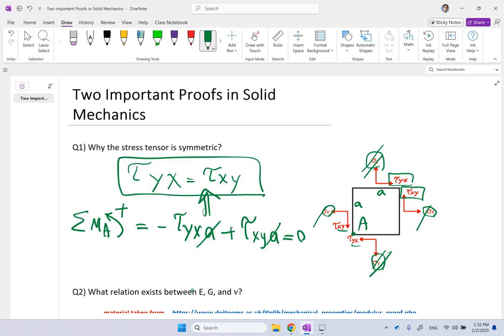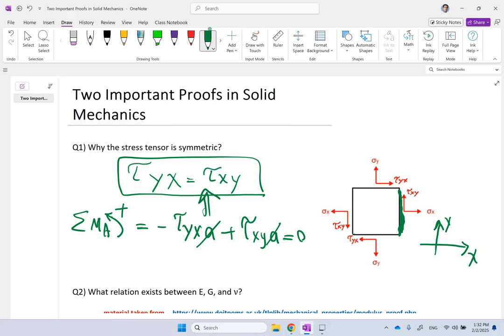And the other thing is the direction of these shear stresses, just so you remember. This is the x-axis, this is the y-axis. So on this surface, where the normal to the surface is the positive x-axis, tau xy is in a direction that is tangent to this plane and in the positive y direction, so it is upward. Similarly, for this face, where the normal is y and the direction of this one is positive x, this is the positive direction to the right.